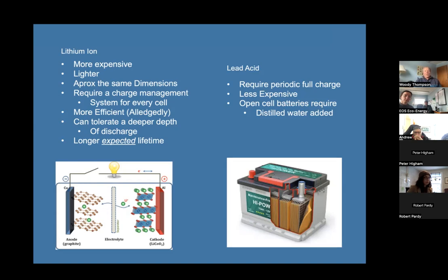And the purpose of that is lithium ion batteries are subject to what's called thermal runaway, where they start to discharge internally. Maybe you've heard about car accidents where firemen have a battery internally discharging and they can't stop the fire it's creating, because the battery is just converting all of its energy to heat, and you have tens of kilowatt hours of energy being released very rapidly. There's no way of stopping it. You just have to wait until it sort of runs out of electrochemical energy and stops making heat.